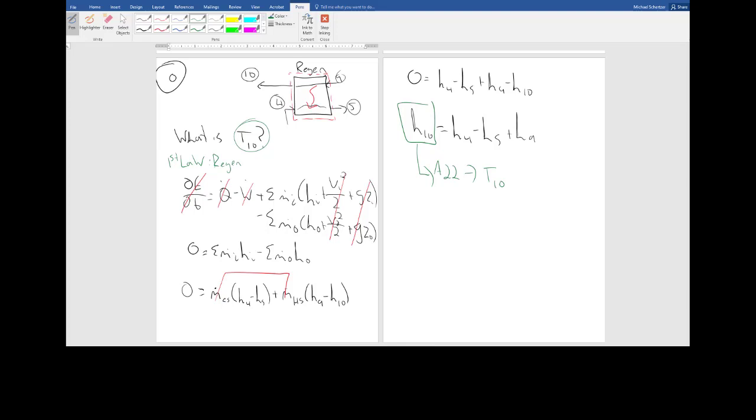So here, the key to unlocking these particular problems is usually knowing where the isentropic processes are. Then you're looking at the isentropic efficiencies to find the real exits of compressors and turbines. You need the regenerator efficiency to fix state 5 in this case. But sometimes you have to skip that if you don't have the exhaust temperature, right?